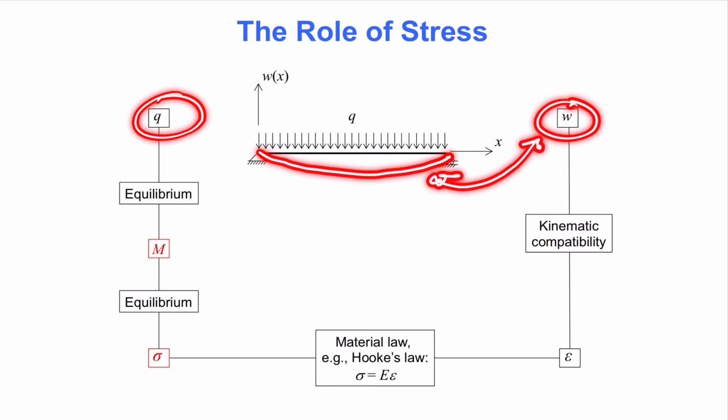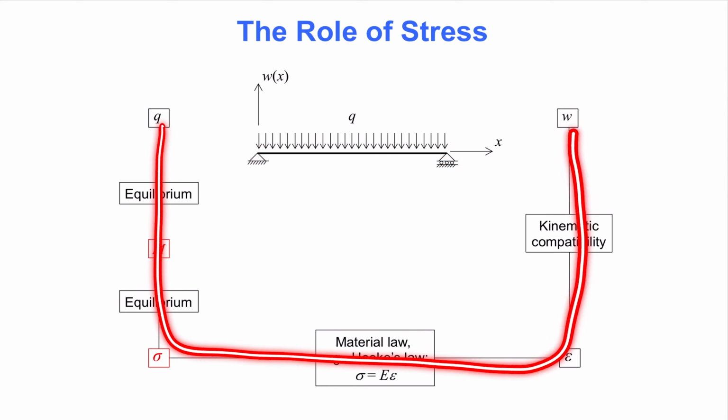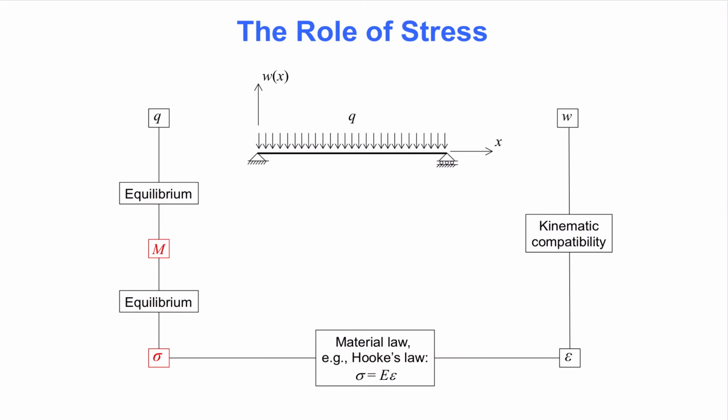Notice this path from load to deflection via equilibrium, material law, and kinematic compatibility. These ingredients appear in all problems in solid mechanics. The only exception is statically determinate structures, for which equilibrium is sufficient.